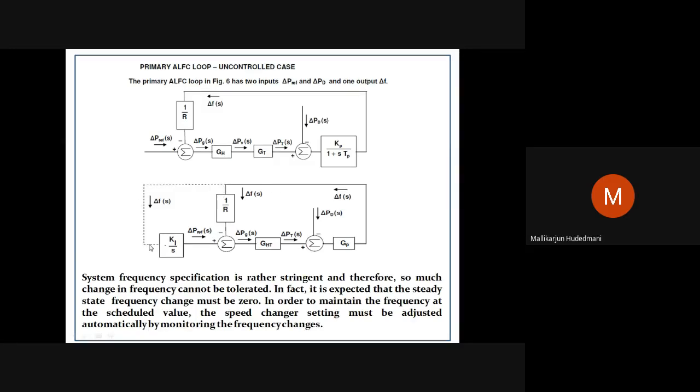This closing is expected. This data, which is the frequency feedback, error feedback, has to be taken carefully. Error needs to be amplified, integrated. Then that should become a reference point changer. This dotted line shows the necessity has arisen. Then that reference point is modified. Again, the primary loop becomes active in the situation. Therefore, this was visualized as the need for the integral controller.